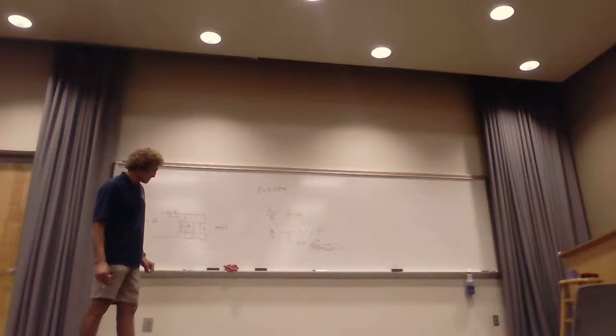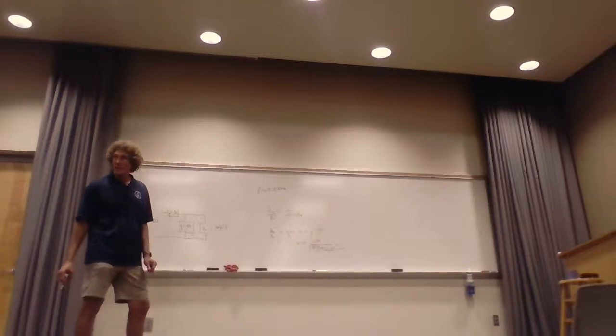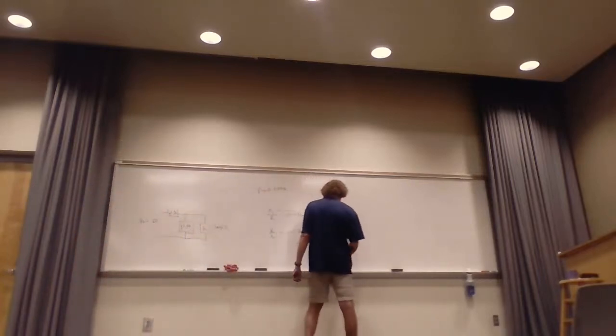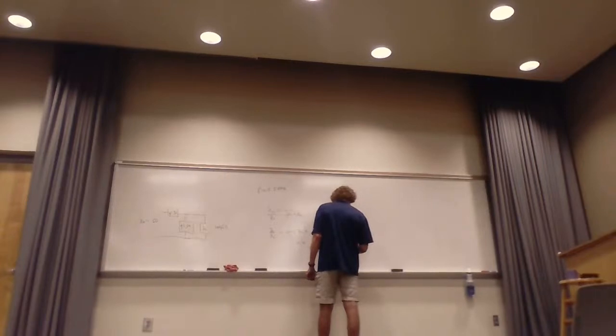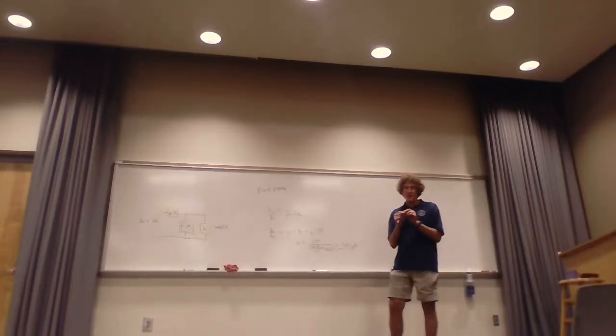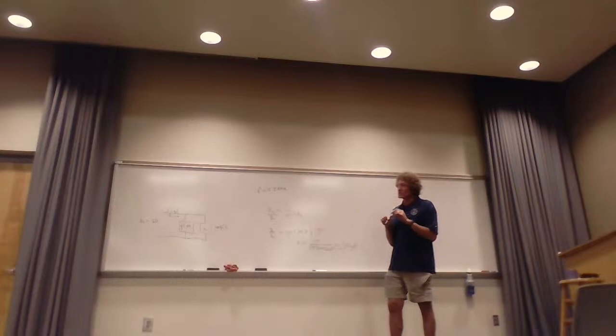Solution. What did you get? Solution says 1.69 picofarads. That's very small. That's what I get. I'll tell you how small that is. Your wire length can change this capacitance from 0.69 to 0.79 just by a small amount at that frequency range. I'm going to say that is not much capacitance. You breathe on it, it'll change.